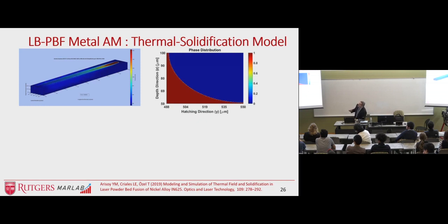That's great. So you can actually see the 3-dimensional thermal analysis, and the temperature gradients are extracted from MATLAB and used in the phase field, and then you can see the phase distribution. This is very similar to when you have water and you put it in the cold, freezing temperature outside, and water begins to crystallize. So that is very similar. In this case, we're working with Inconel. So it's a multi-material, it's more challenging, but it's the same idea.